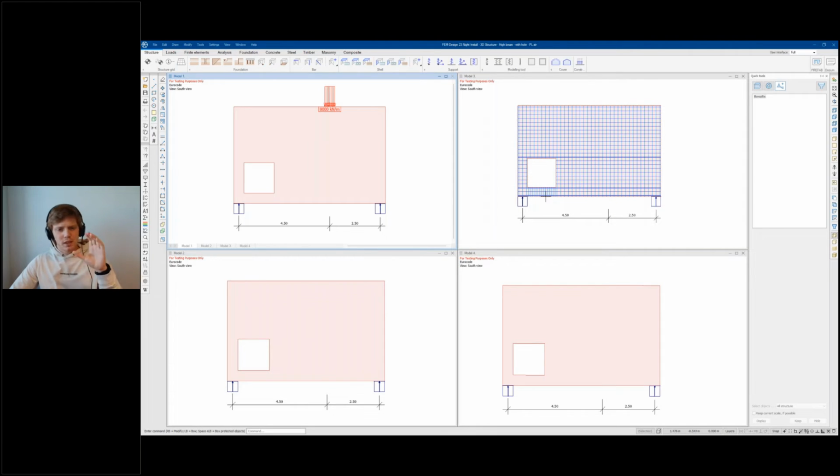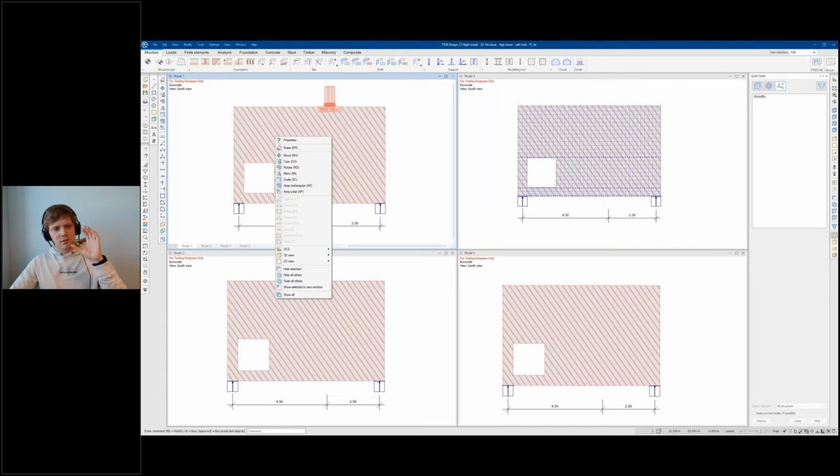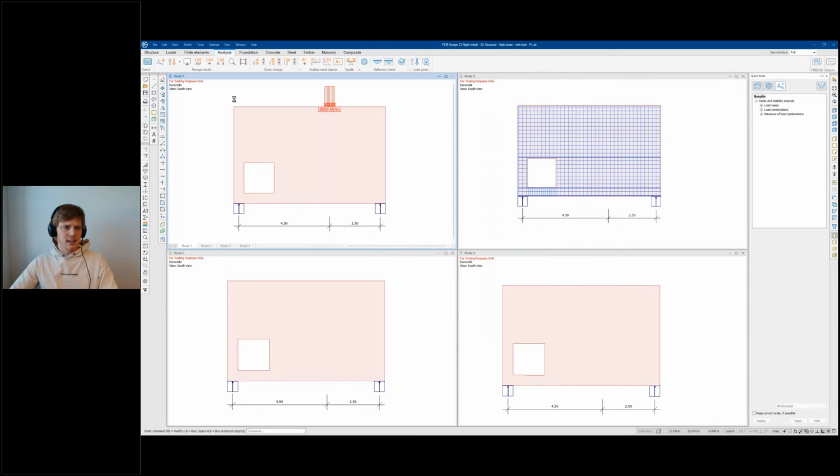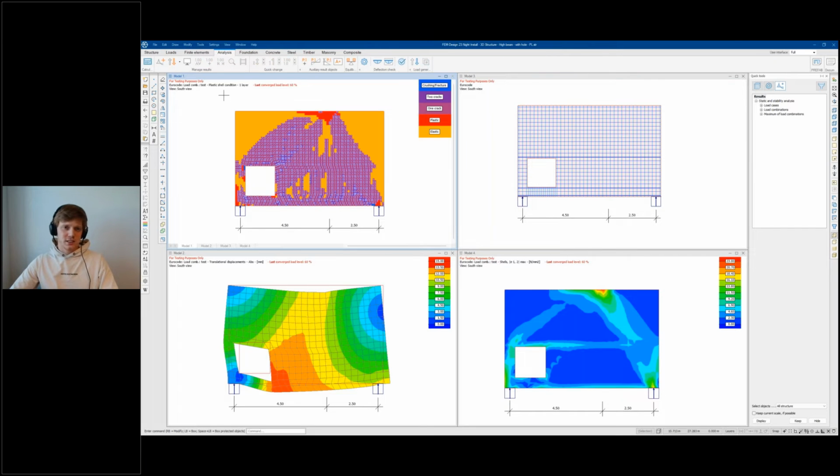All I did was go inside and turn it on, exactly as I showed you. So I turn on settings in here, and I do the plastic analysis, and it is quite fast actually. You can of course change a lot of settings. In this case, you will see how this one works. I'm pushing this one to the limit. I tested some stuff, and I'm putting on more load than I know this wall can take, just to get the final load step level. So I can use this to evaluate what is the maximum capacity of this wall system.